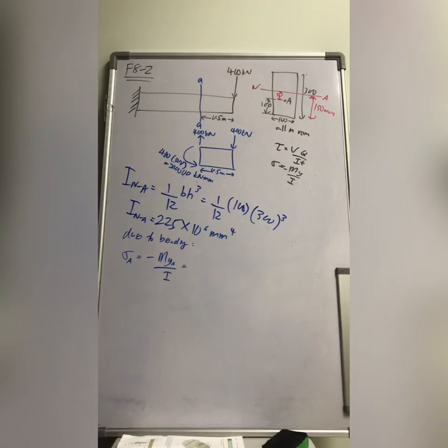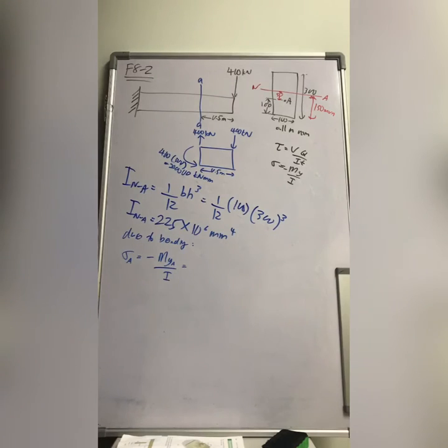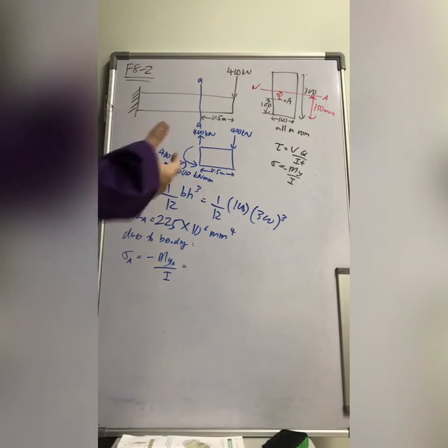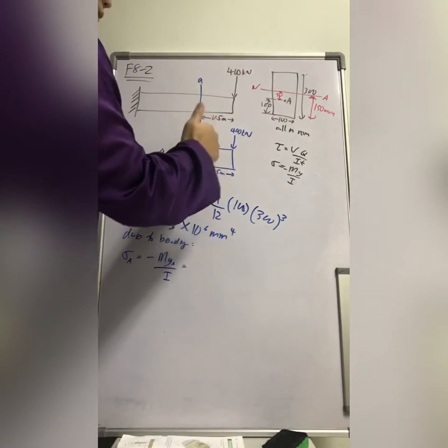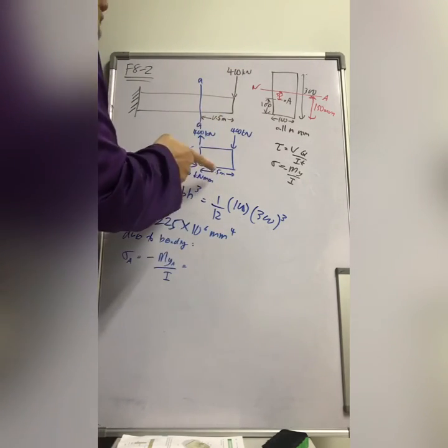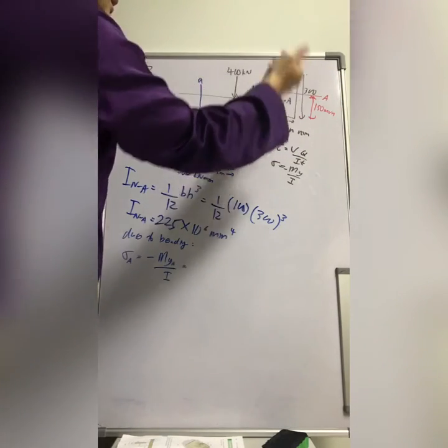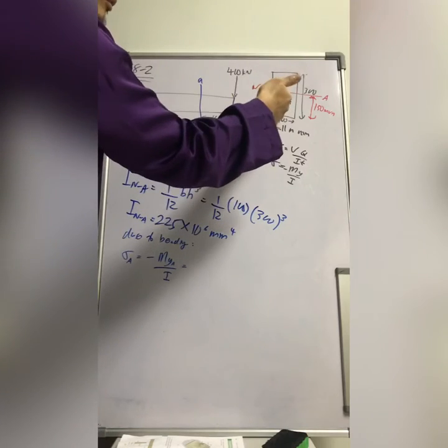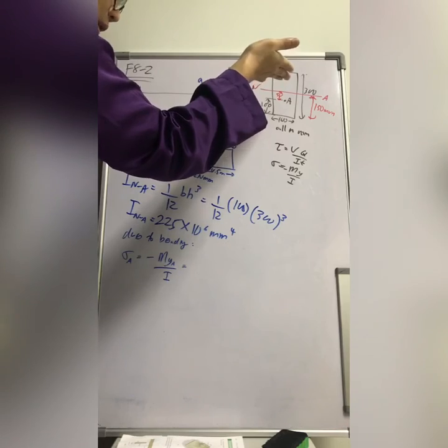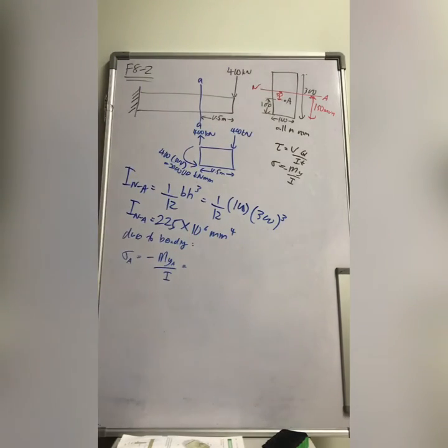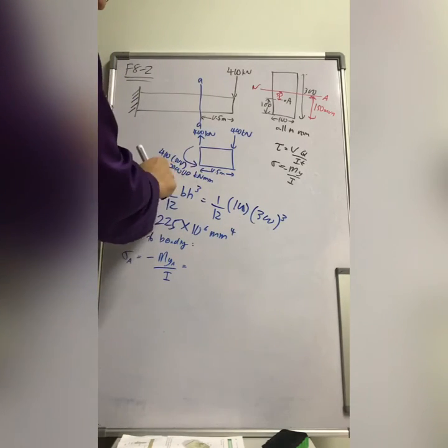Here, for this point, is the bending stress minus or plus? The answer is minus, compression. Why? Because, as you can see here, top going tension, bottom going compression. The neutral axis is 0 for bending stress, of course. So A, being at the bottom, undergoes compression. Otherwise you need to use M positive going up with this minus value.